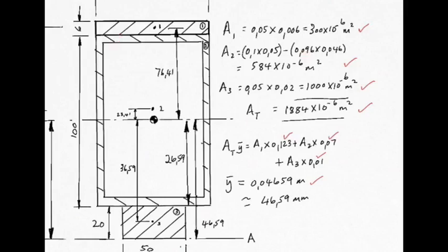Okay, so that is the distance from here to here, 96 millimeters, multiplied by the distance from here to here, which is 46 millimeters, which you obtain by saying 50 minus this piece leaves you with 46 millimeters. So there is the total area of this bit here, which is the hollow rectangular cross section. All of that area is that much. So the total cross-sectional area of the entire composite beam is that.